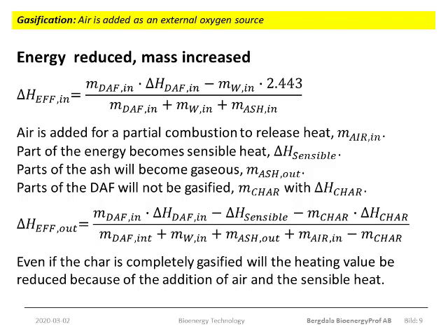If the gas is cooled, then the total energy in the gas is reduced by the sensible energy, and the total mass may be reduced by condensation of the water. But generally speaking, the heating value will still be lower in the product gas than in the incoming biomass. But even so, the gas may well be a better fuel than the solid biomass.